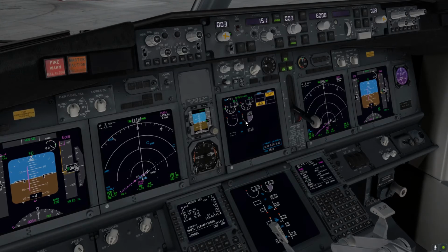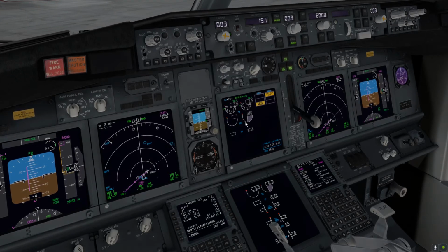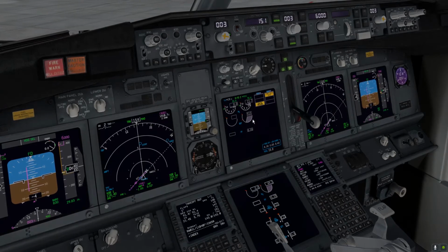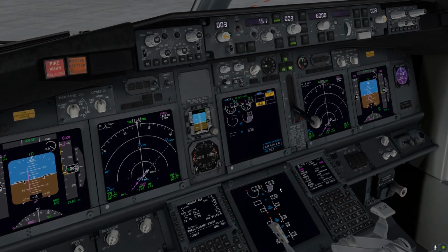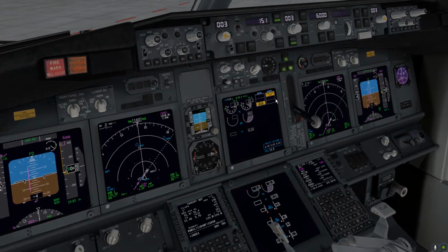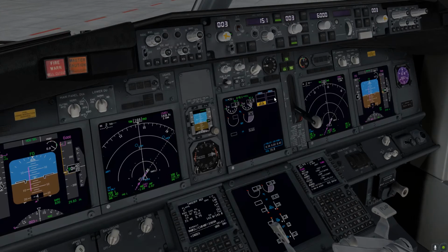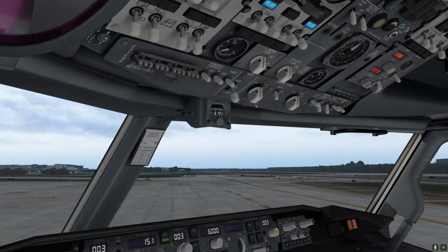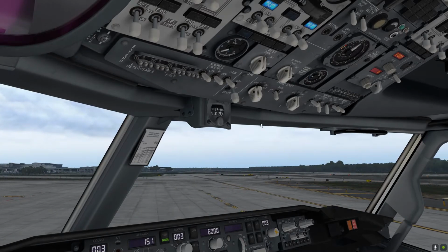So let's observe that the EGT is not increasing too much. And now looking back into the N2, waiting for 56% when the start valve goes out and it's started, cut out. So let's go ahead and repeat the same for engine number 1. Start engine 1.